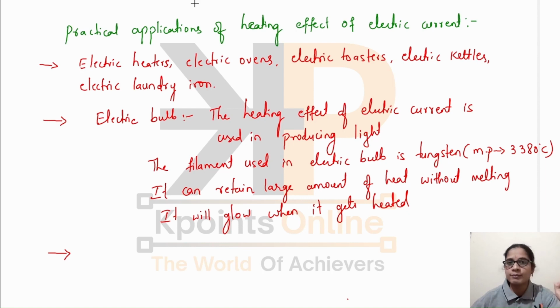Usually a fuse is made up of a metal or an alloy having an appropriate melting point. When a large amount of current more than the specified value passes through this fuse, the wire present in the fuse will get melted. So the circuit will be broken and the current will not pass through any appliances, and it prevents short circuits.